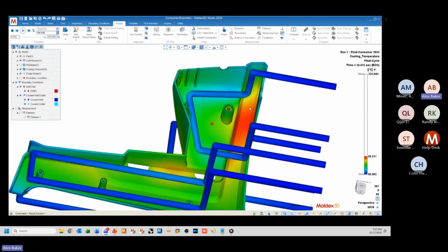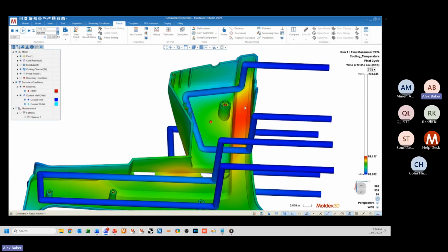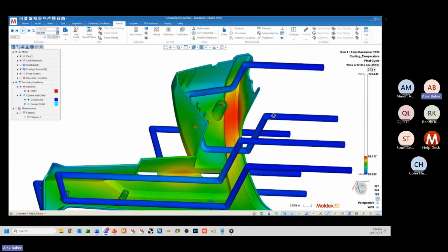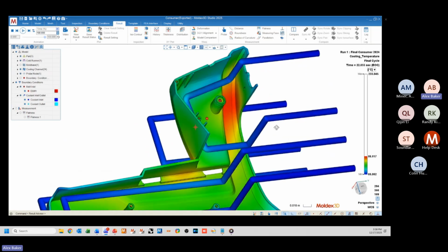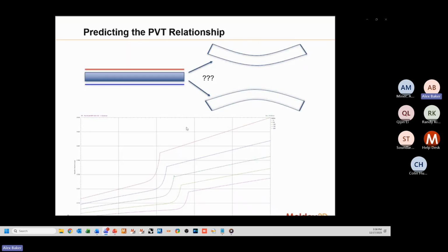You would almost think that the heat would be attracted to this cooling channel, but it is not. It is actually going to prefer, to personify it a little bit, to stay in the mold, and it will accumulate over a large number of cycles. This is going to create a hot spot in the mold, therefore a hot spot on the surface of the part, and therefore a differential temperature of the part that will apply similar to our example from our plaque.